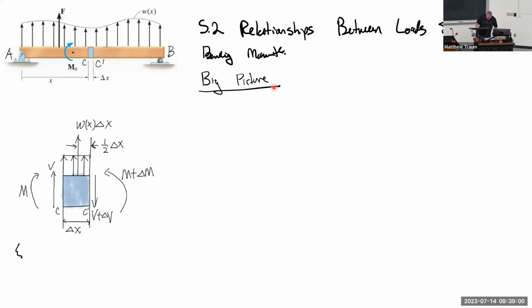So there is no need to evaluate every location on a mechanical member to determine whether it's going to fail or not. If failure doesn't occur at that maximum shear or maximum bending location, then it's not likely to occur anywhere else. And so you can basically be the smartest person in the room, right? Everybody's giving their design reviews and presentations, and you can do the calculation and show this isn't going to fail. And people with their finite elements and their calculators and all that stuff are wasting a ton of energy, and you basically solve the problem with a single calculation. So that's where we're going with this, is trying to make it as easy as possible for you to get to the right answer, which is that this part is not going to fail under these conditions.